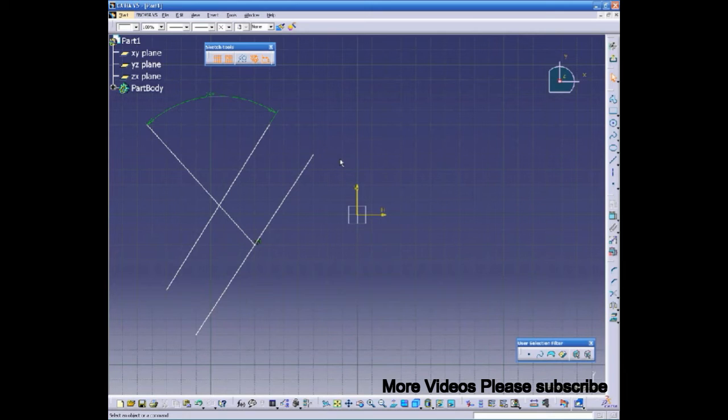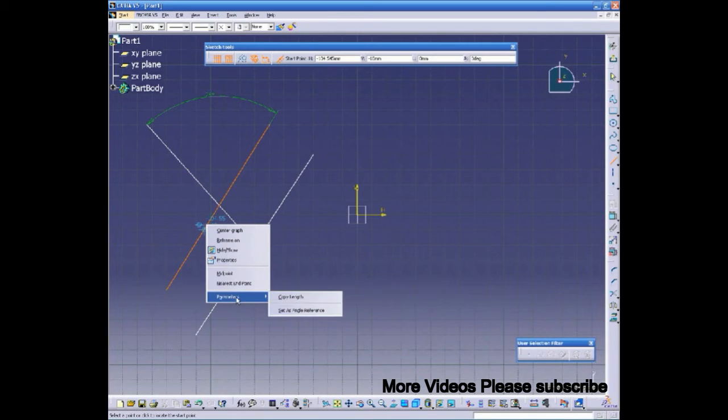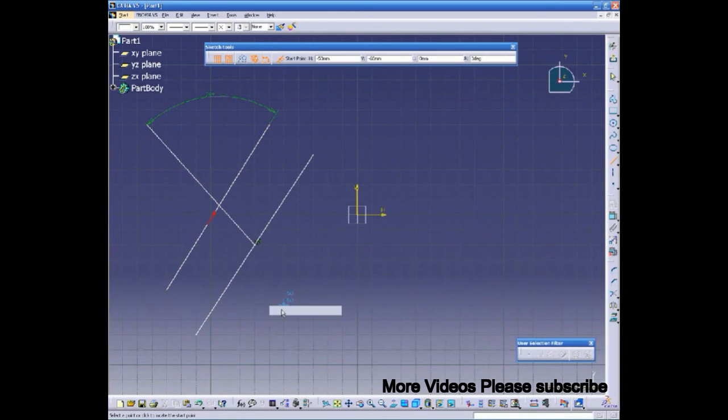I will create referenced 45-degree symmetrical line. Click the line icon. Make sure the Symmetrical Extension command option is activated. Right-click this line and select Parameter. Then set as Angle Reference.